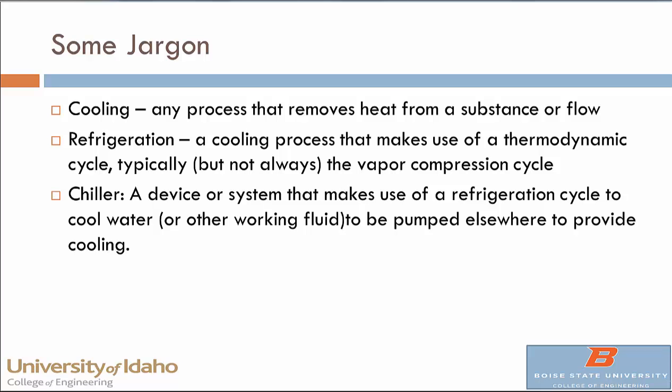And just to wrap up this introductory lecture, let's talk about some of the terms we'll be using. This is a course on process cooling, and that refers to pretty much any way in which we can remove heat from a product, a thing, or a flow, right? Now, refrigeration is a subset of that, and it specifically refers to a type of cooling process that uses a thermodynamic cycle, and it's almost always the vapor compression cycle.